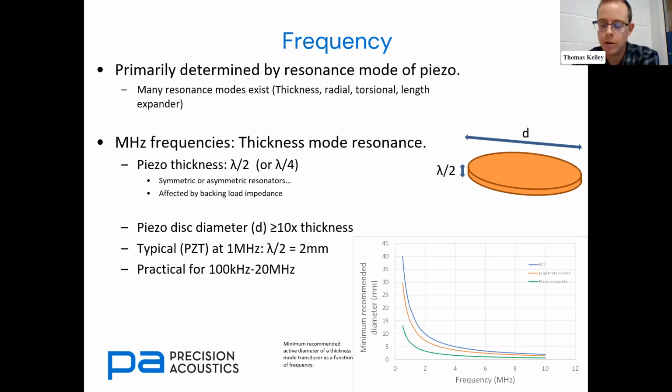We were looking there at a film thickness of 9 microns. If you consider that in the parallel plate capacitor expression, you have an incredibly high capacitance, and it's in your circuit. It's inherent. You can compensate for it, but you can't take it out, and it weighs very heavily on the frequency of the transducer that you build with the film.